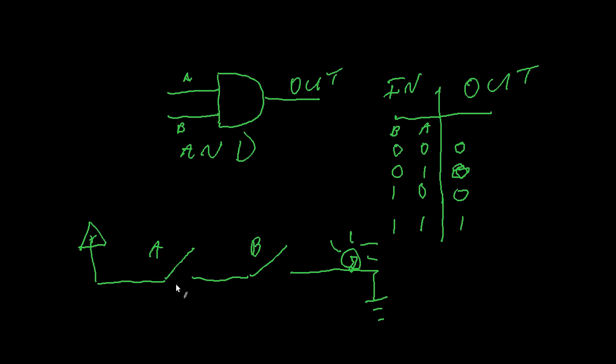So you could do this directly as relays. Now, when we're doing transistors and such, the actual internal circuitry gets a little bit different. But if we were using relays, this is exactly what you would be looking at. You'd just put the relay coil down here, and it would look exactly like this diagram.